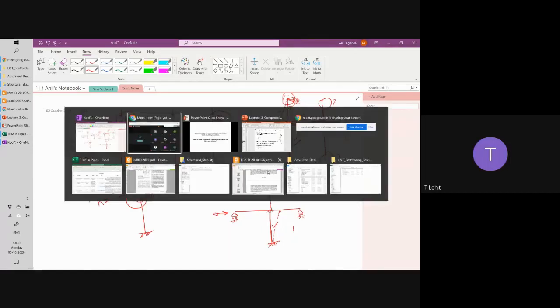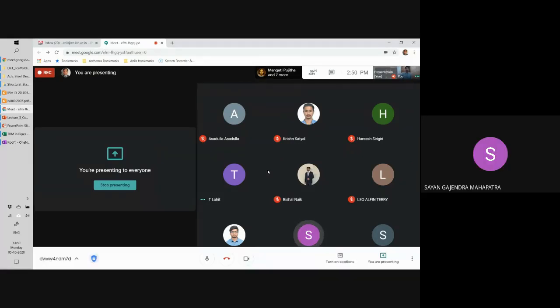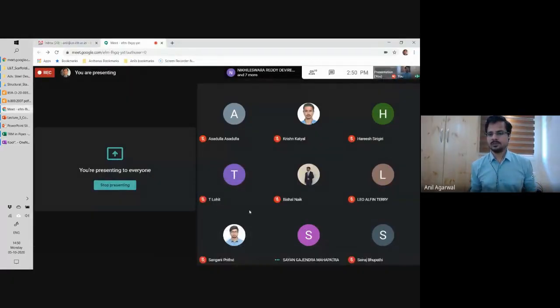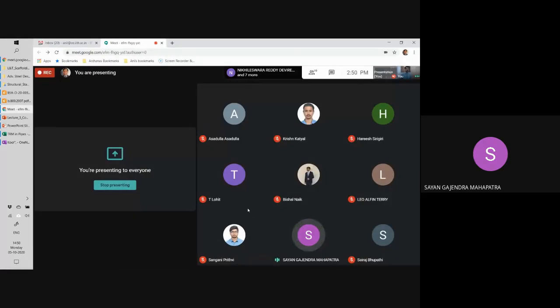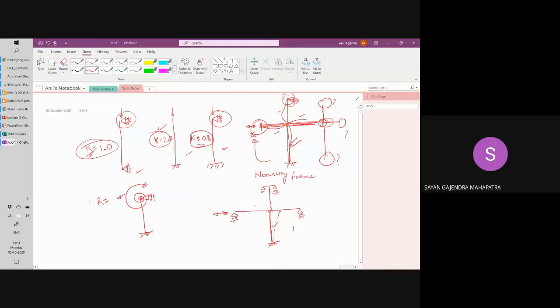I heard a couple of other students saying something, but I overspoke them. 0.7, sir. 1.5. One at a time. Who's at 0.7? Shayan? Me, sir. Shayan, why is it 0.7? Sir, because one end is fixed and the other is pinned.